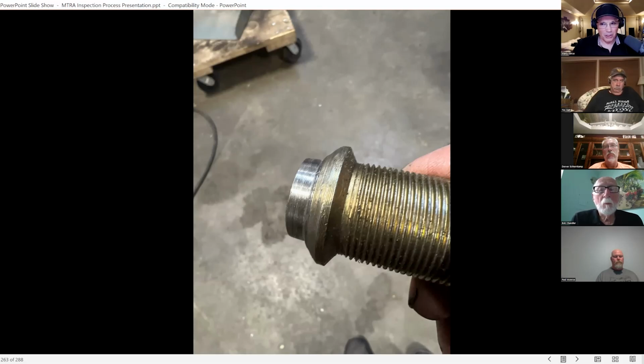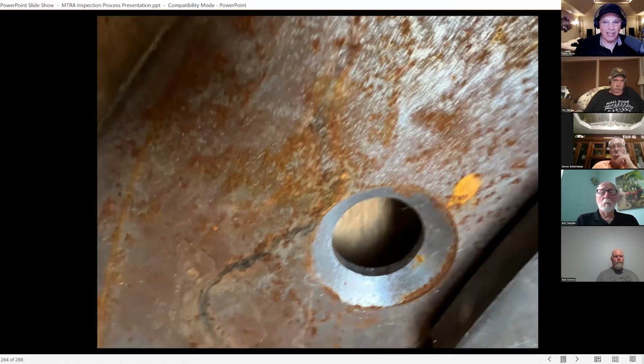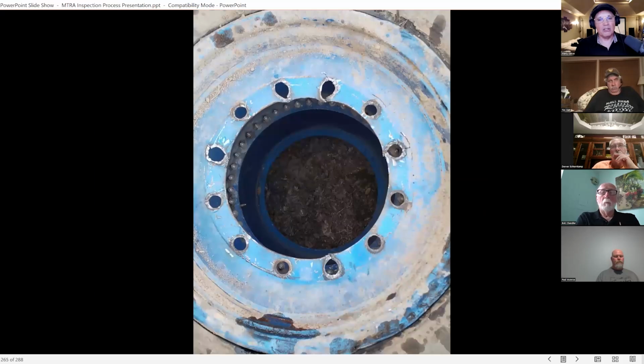So just picture in that last example that you saw, if the surface of that lug nut is countersunk already, that wheel is grabbing less than 1/8 of an inch of material there. That taper, you see how thin the wheel gets when you start tapering that in? That other wheel was tapered further than this one. So that inner material is really thin. And we have seen so many failures lately where the wheels will pull right through the lug nuts.